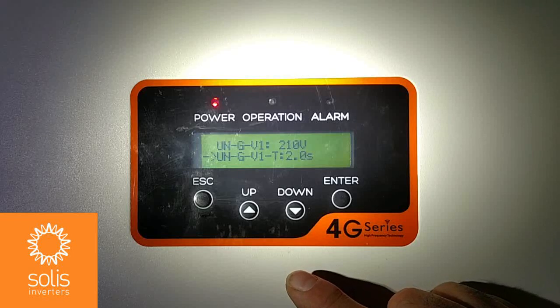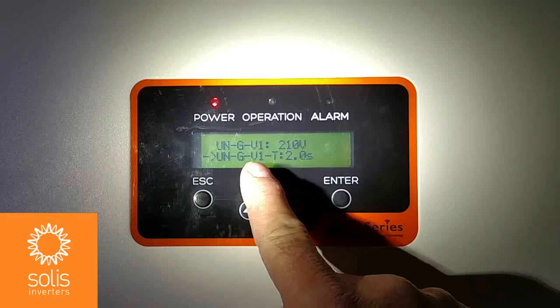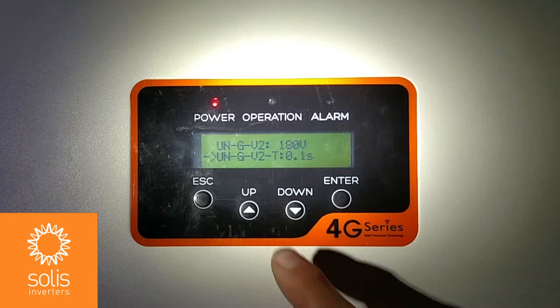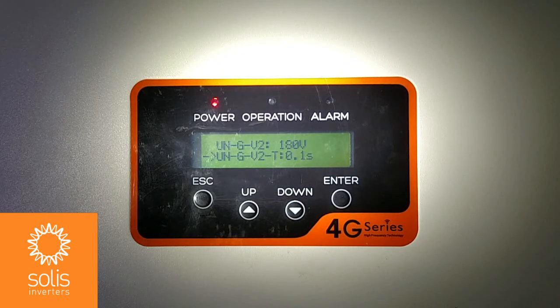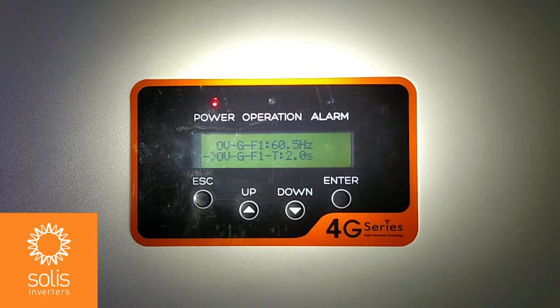This one is under grid voltage. This is again 1 here indicating our intermediate limit. So 210 sounds good for 2 seconds. And then we have our absolute limit set for 180 volts at trip time of 0.1 seconds. That all sounds good.